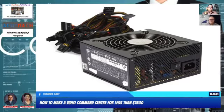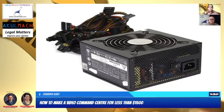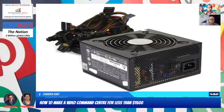And also in case of surge. Usually when you buy a standard ready-made PC, you will get a 500-watt power supply. It is sufficient, but since you're building your own using these instructions, go for 650 watts. There is no need to buy an 850-watt power supply, but you can go slightly higher so that there is more resilience in the system that you're building.